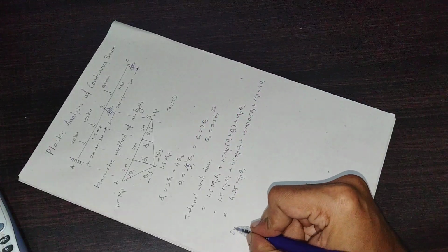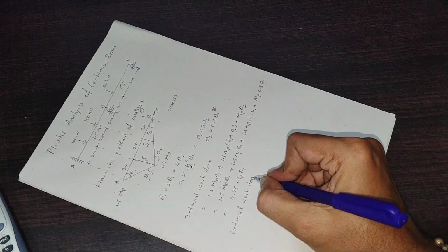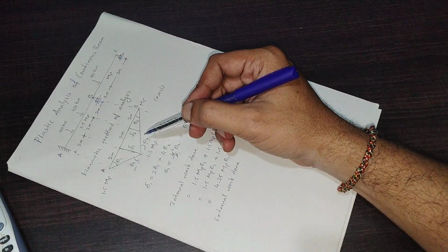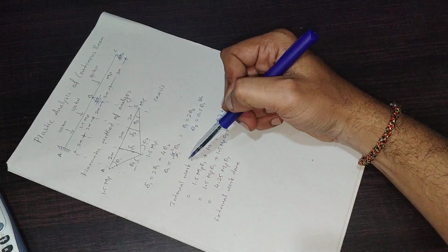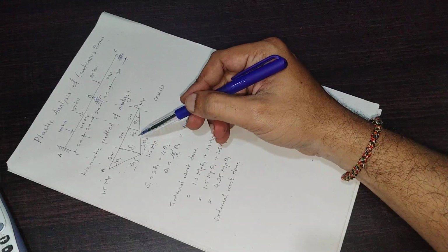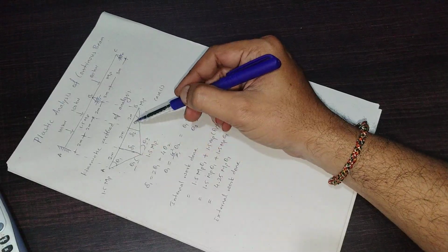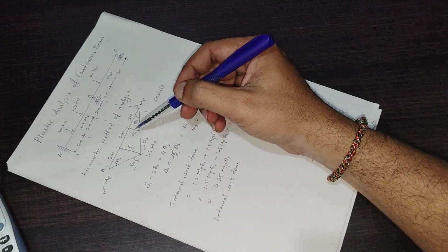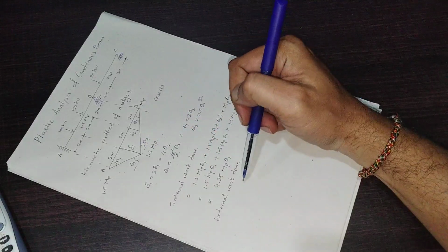Similarly, I need to write it for the external work done. For this external work done, what can I do? Now in this case, I want to take the relation between delta 1 and delta 2. As I have taken internal work done for theta 1 and theta 2, for the external work done I need delta 1 and delta 2, because internal work done is measured through rotations and external work done is measured through the deflections under each load. In that case, I am considering delta 1 and delta 2 for external work done.